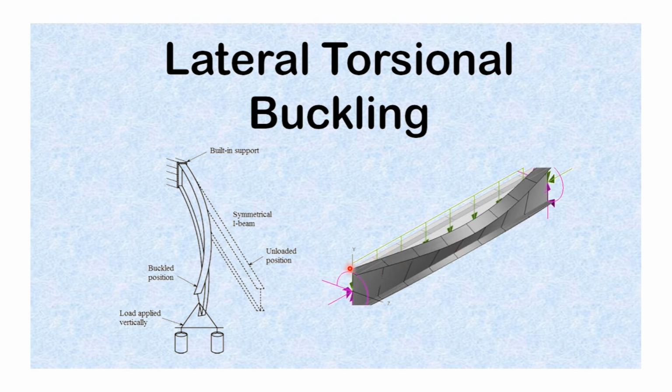Okay, so if there is some bracing or some arrangement that can stop the twisting, that will act as a controlling criteria for resisting lateral torsional buckling. So again, we will discuss lateral torsional buckling in more detail in the next slides.